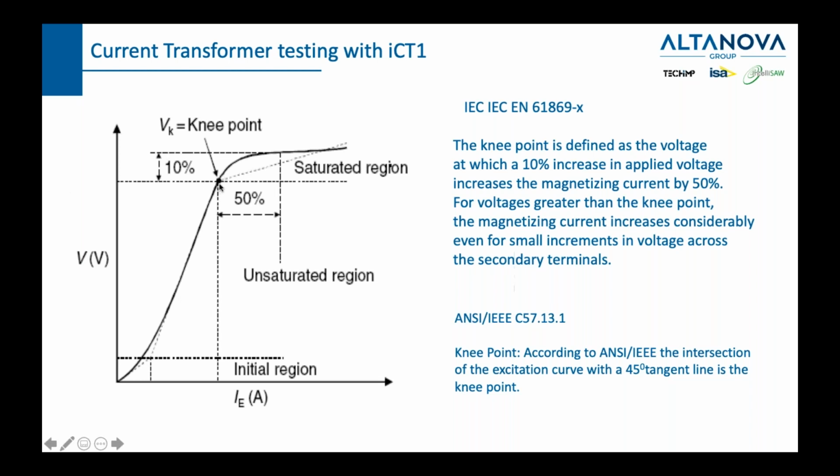They definitely describe the inflection point at which this straight line stops being a straight line. Basically, the point is this: you always want your CT to function in this region here, where it's proportional, and you don't want it to function here where it's not proportional. So we always want to avoid saturation.